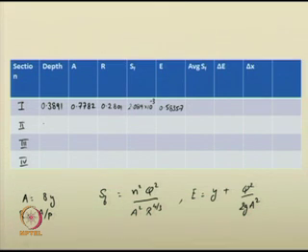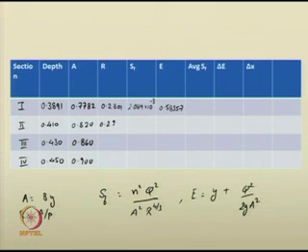Substitute this form here and I am getting 0.58357. Similarly, for section 2, the corresponding depth is 0.41, at section 3 the depth is 0.43 and at section 4 the depth is 0.45. You can see the corresponding area also. The corresponding hydraulic radius is coming to be 0.2908 here, 0.3007, 0.3103.